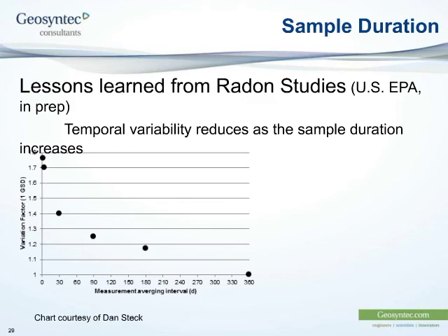One common problem with both of them is that there's a limit to the duration of the sample that can be collected. If you talk to somebody in the radon industry, they refer to a sample of 90 days duration as a short-term sample. And they're often collecting samples over a period of a year to get a better time-weighted average concentration, more representative of long-term averages.